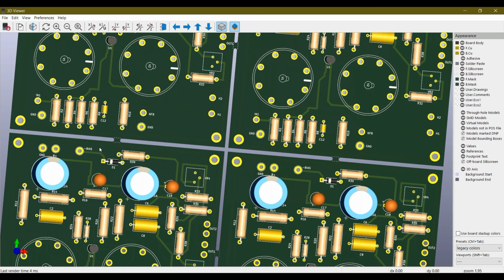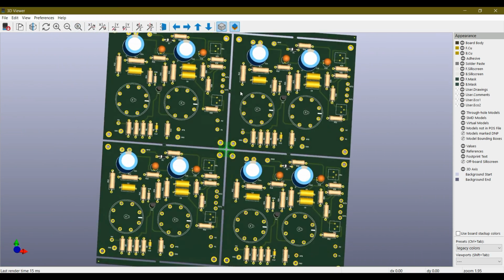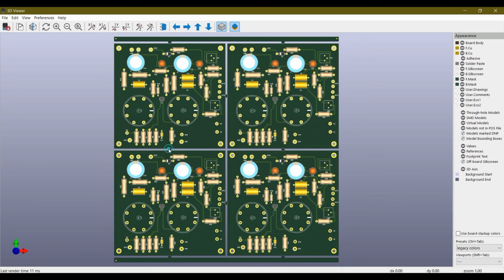You can easily break this PCB from this mouse bite. Let me do this. So you can break this PCB from this mouse bite, or from here and from here. Similarly this one from this and this. In this way you panelize your PCB. Panelization helps us to speed up the assembling process, as well as the frames just added on the sides of the PCB will help us to put this on the conveyor belt and pass it into the reflow oven.